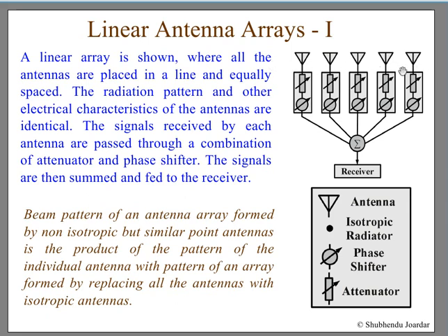This is a one-dimensional array, in a straight line. You have an object at a very far distance, at some angle. You can control these phases to steer the beam to the right or left, of course within a certain angle only. You cannot do it for more, and it is also restricted to a single frequency or a very narrow bandwidth. You can do beam steering that way.